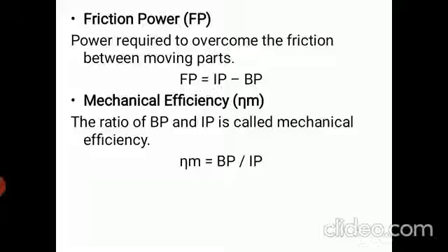Then the valve mechanism has some friction. If a fuel pump is used in the cylinder or engine, that also has some friction. The amount of energy that is wasted to overcome these frictional forces is termed as frictional power. Theoretically, if you want to calculate how much power is wasted in overcoming these frictional forces, you subtract brake power from indicated power, and you will get the frictional power. So the difference between indicated power and brake power is termed as frictional power.